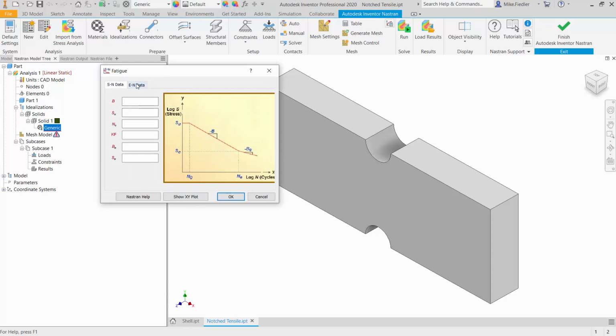So we accommodate two different types of fatigue. There's your SN data, or your stress-based fatigue that can be done. The inputs here are pretty straightforward, right? They just correspond to the graph. You can input your slope right there, your intercept stress level S sub u, the intercept cycles, your reduction effects, and so on. And basically you're inputting this curve, and you can perform a fatigue analysis. And it also accommodates strain life data as well. So stress life data generally used for high cycle fatigue, and then strain based whenever it's a low cycle fatigue problem in general.